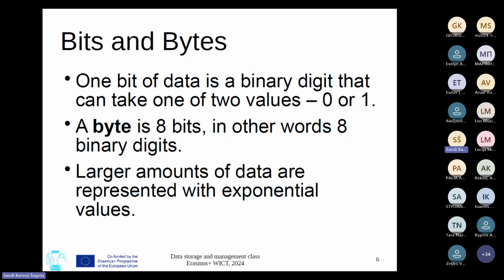If you are trying to do something like that with 10 values, in an area of 0 to 5 volts, now you suddenly don't have 2 volts of space that defines a 0 or a 1. You suddenly have 0.5 volts, and it's much harder to be that precise.